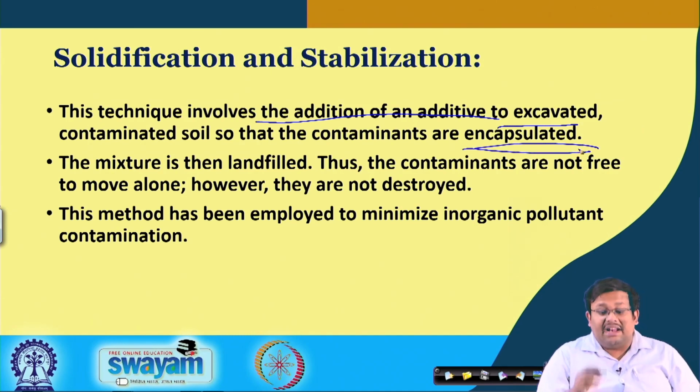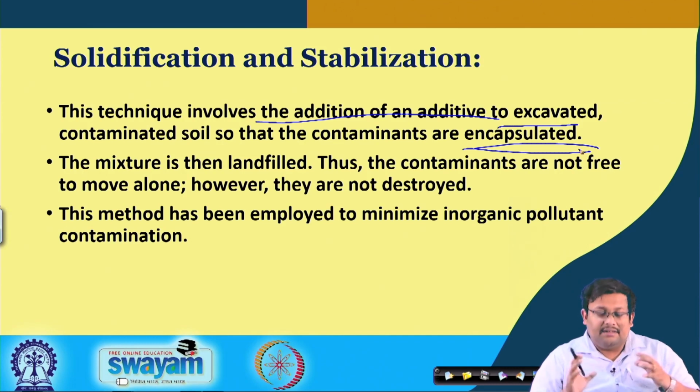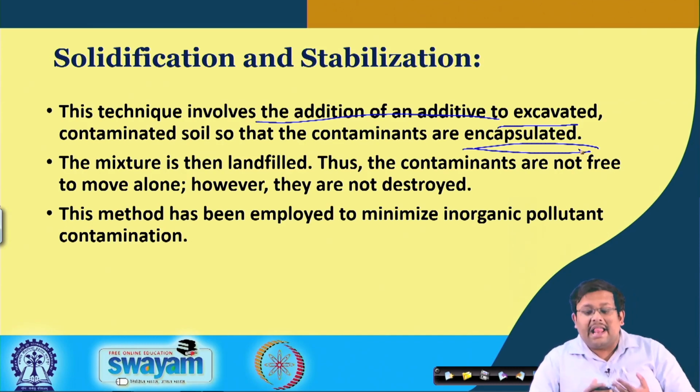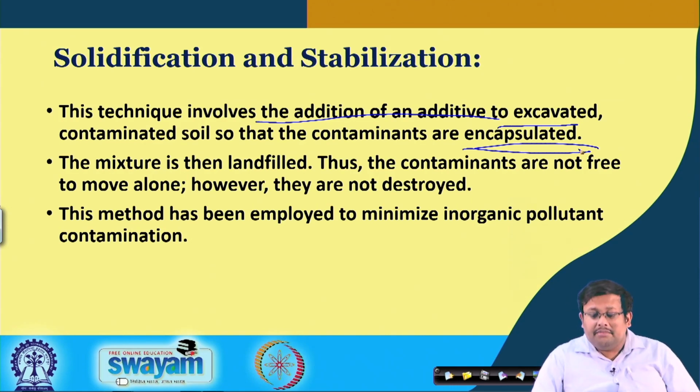The mixture is then landfilled, so the contaminants are not free to move along. However, they are not destroyed. They are contained in the landfill region after being encapsulated with the help of these additives. However, this method has been employed to minimize inorganic pollutant contamination in some places.